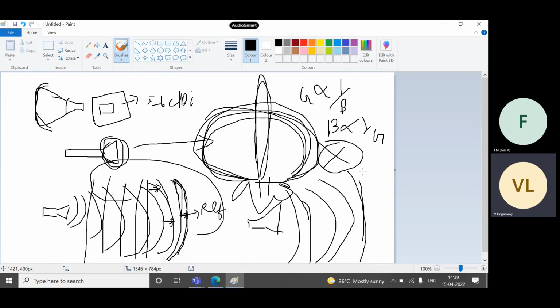Because the problem is, for example, you are having one antenna like this that can receive these rays. If you are having spherical waves like this, then you are getting phase deviation, right? That's why we always keep antennas far away, at the far field distance.